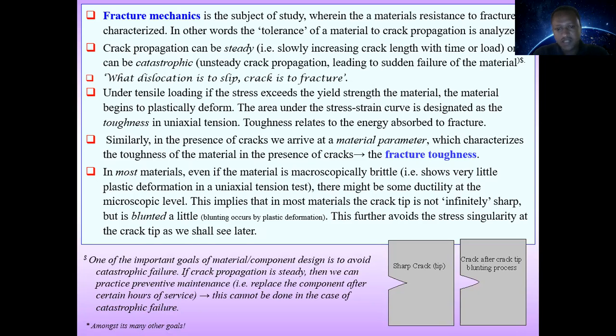If the crack propagation is steady, then we can practice preventive maintenance. That means replacing the component after a certain number of hours of service. This cannot be done in the case of catastrophic failure.